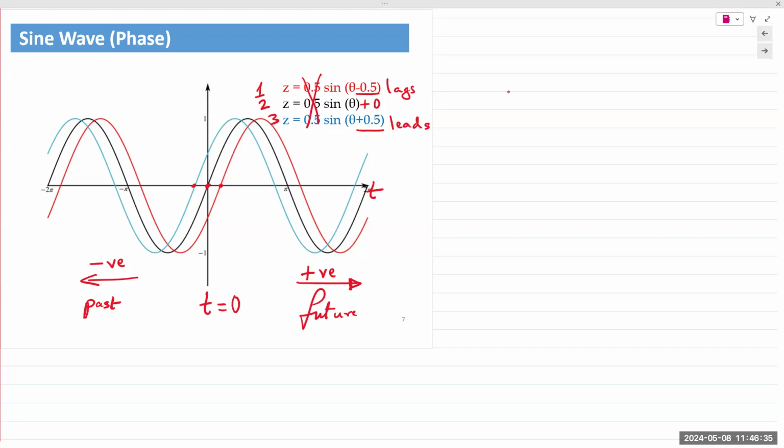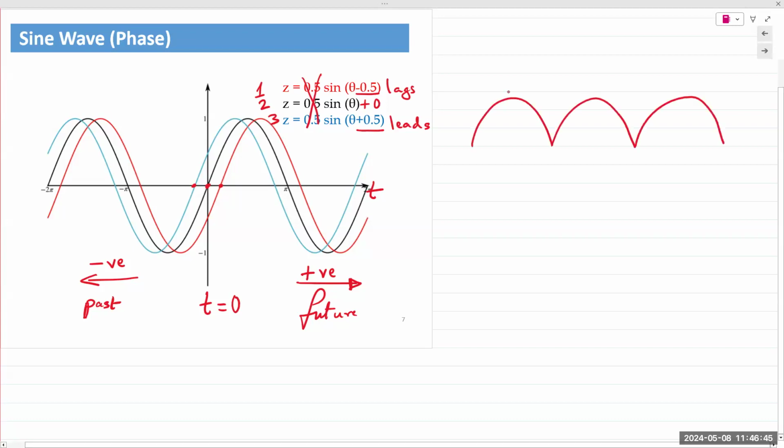Think of it in these terms. If you have all the negative peaks, flip them on the x-axis. If there are mountains of dirt and you flatten them out, what value would you get? It would be kind of an equivalent DC value that would produce the same energy. You take the negative and the positive values, the mountains of dirt, you flatten them out, and you get a new value.